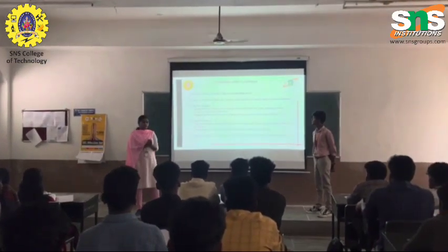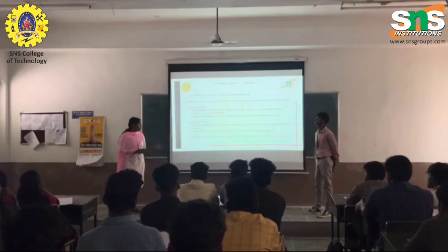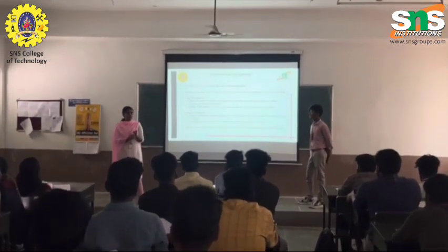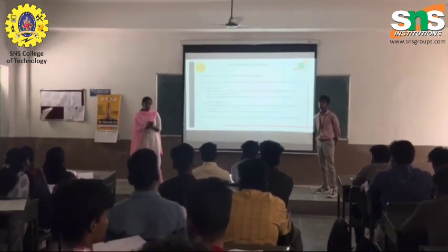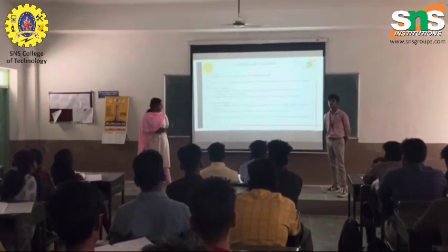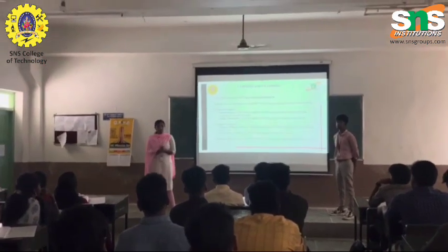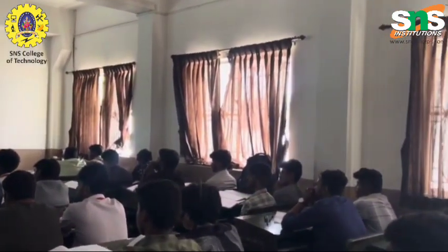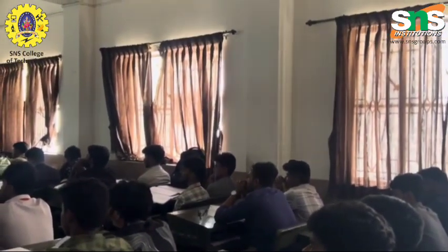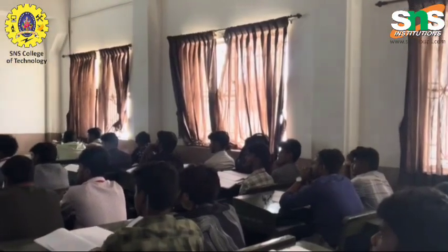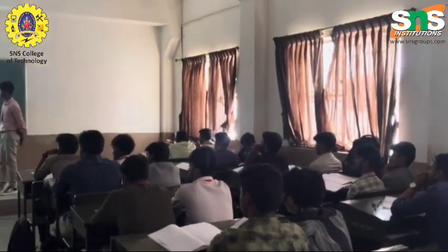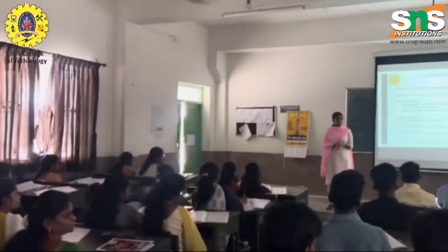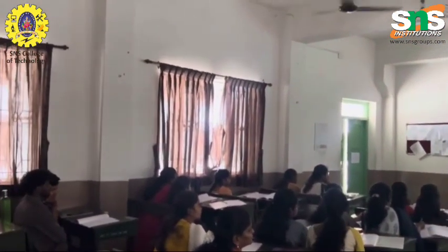And in testing, we are going to evaluate the circuit performance. Here we have to verify that the clipper successfully limits the signal amplitude without introducing unwanted distortion, and checks the clipper accuracy at the voltage level. And for testing clampers, we should ensure that the clamper shifts the signal to the right DC level without changing or altering its waveform. Based on these tests and results, we can refine or restructure the circuit design to improve its performance.